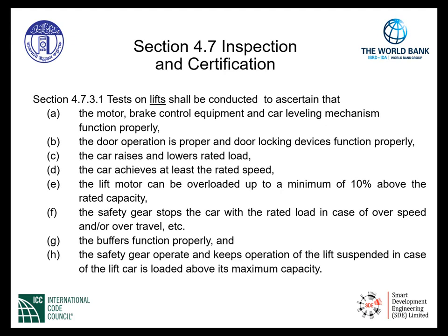F, the safety gear stops the car when the rated load is in case of overspeed and or over travel, etc. G, the buffers function properly. And finally, H, the safety gear operates and keeps operation of the lift suspended in case the lift car is loaded above its maximum capacity. These are the tests on the lifts that need to be conducted for safety functions of lifts.